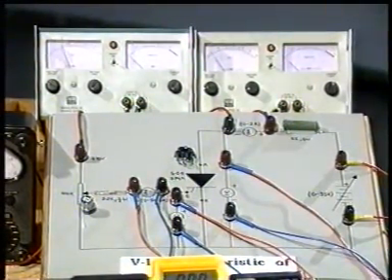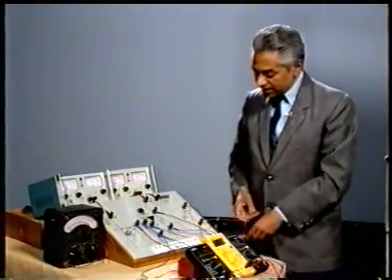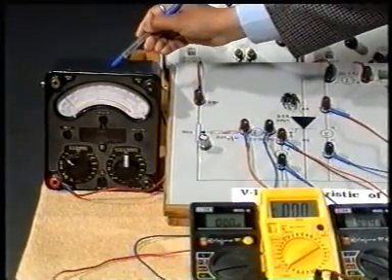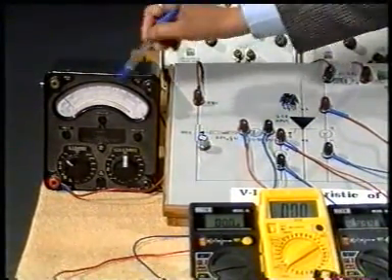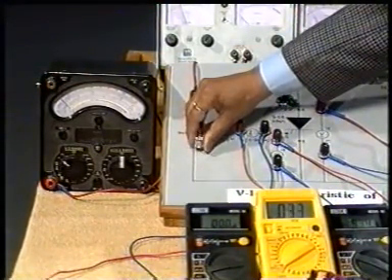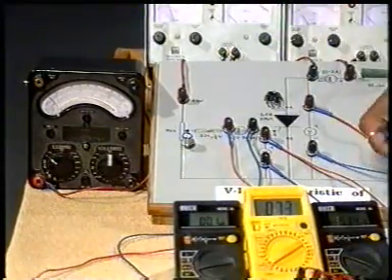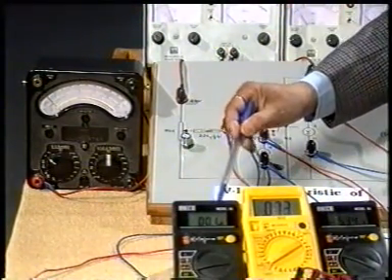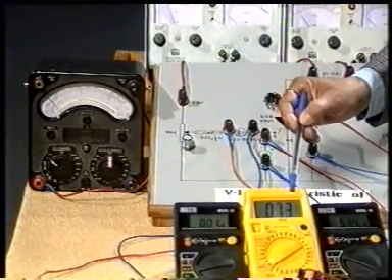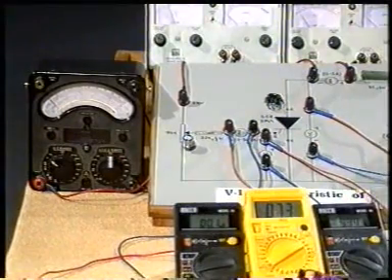At this setup, I am going to see when the SCR is triggering. For that, I am going to use this potentiometer. Now, you will concentrate on this analog multimeter, because at the time of triggering, this will show you a kick. You see, I am increasing. Of course, you can also see, yet it has not triggered. This is the multimeter, which is an ammeter. It is showing 0.1 milliampere, that is the gate current. This is the gate voltage, about 0.73 volts, and this is the voltage applied between anode and cathode.